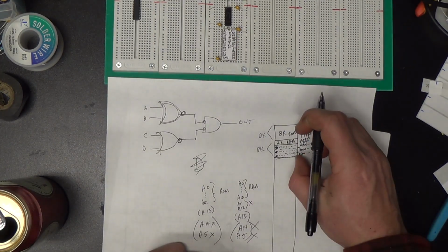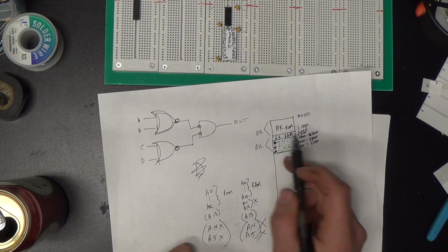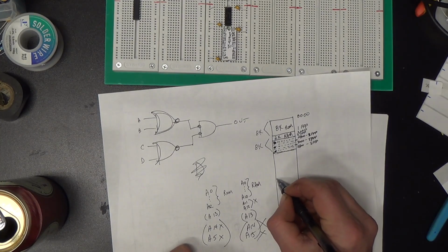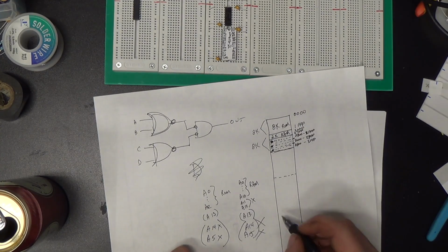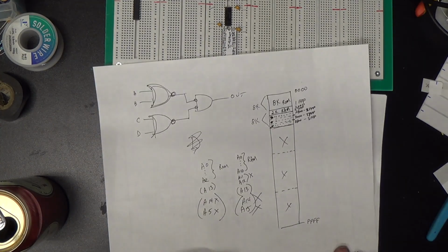That also means that this whole 16K block, containing the ROM, the RAM and the mirrored RAM, will also be mirrored up through the memory map 3 more times.